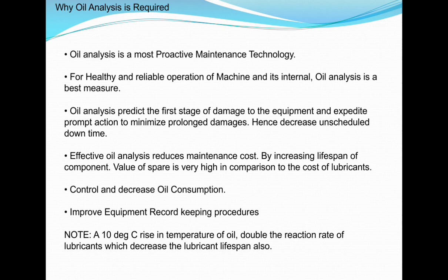And a 10-degree rise in the temperature of oil doubles the reaction rate of the lubricant, which also decreases the lifespan of the lubricant. This is why we need to do oil analysis.